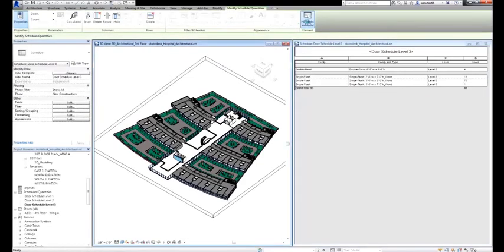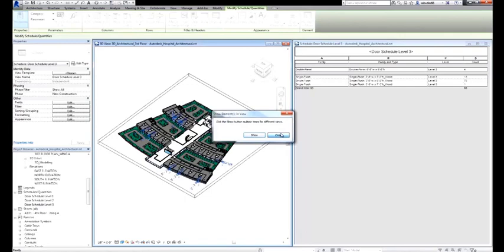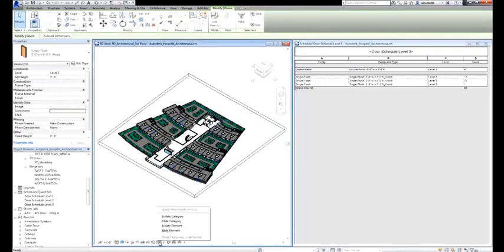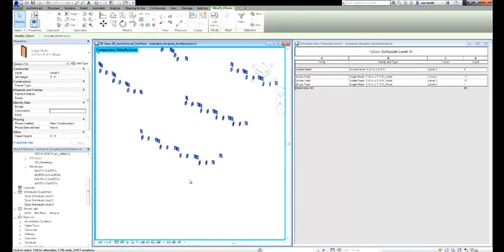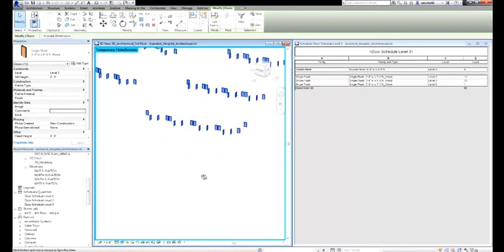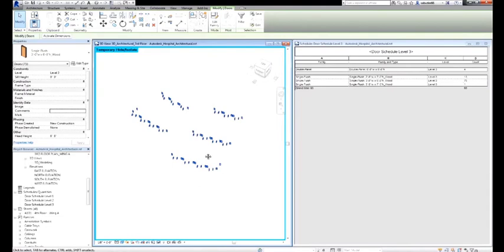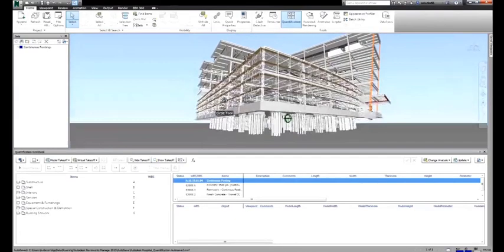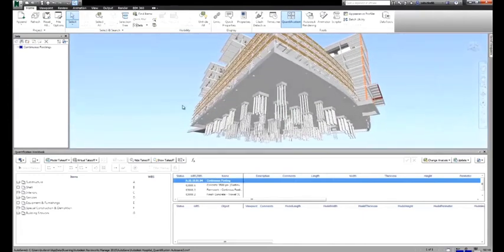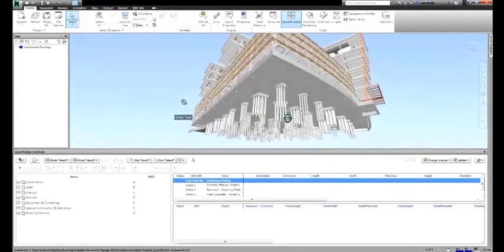Here we can see how Autodesk's solution provides several ways to gain access to the quantity information early in the planning process. By leveraging tools directly from Revit and Navisworks, we can quickly get a high level of understanding of the project quantities. Schedules or tables of data built from the 3D model created by the designer can be used by adding counts and totals, or a custom table can be generated on the fly to give you feedback and quantities from the model information immediately.